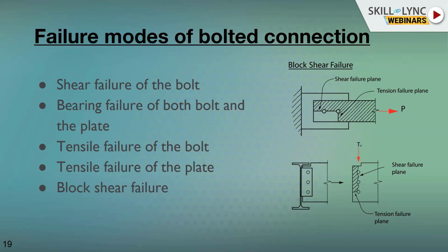If you tear one of the papers from that spiral, you may observe that the first crack happens at the top, and then the portion of the paper left on the side of the spiral continues to tear away, and you get a paper with half the spiral hole in it. The portion left out from the spiral on the other side exactly explains the concept of block shear failure in steel.